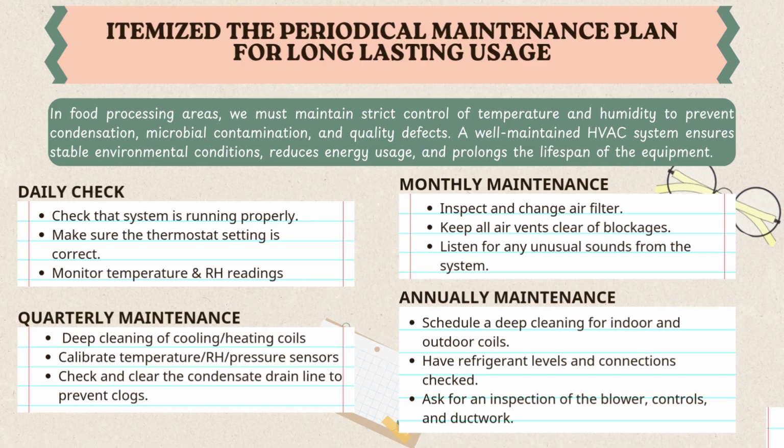Next, quarterly maintenance requires deeper technical servicing, including cleaning cooling and heating coils to improve heat transfer efficiency, calibrating temperature, relative humidity, and pressure sensors to ensure accurate environmental control, and clearing the condensate drain line to prevent water buildup and mold growth.